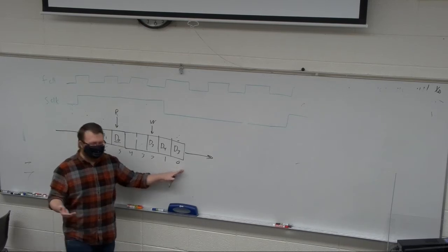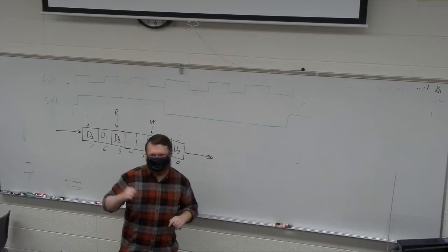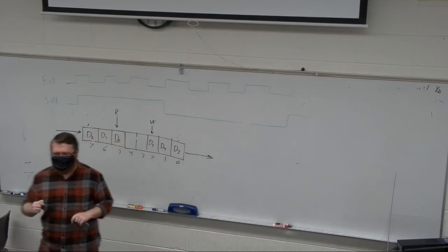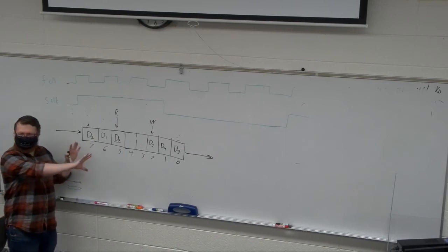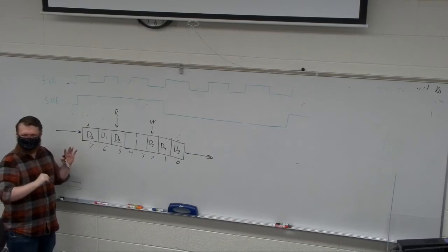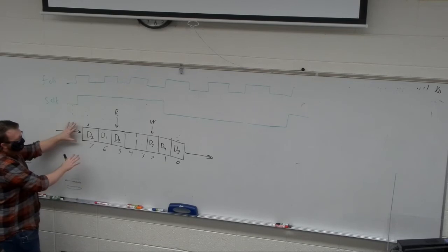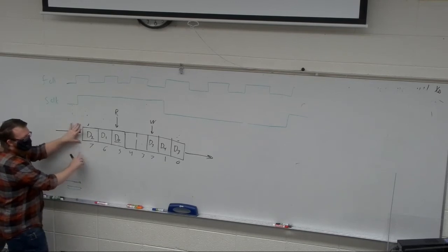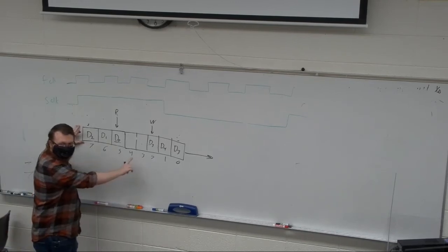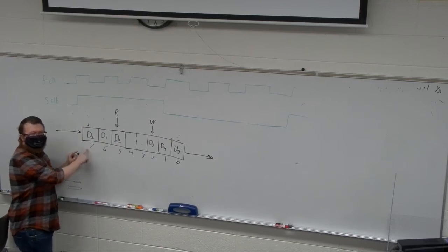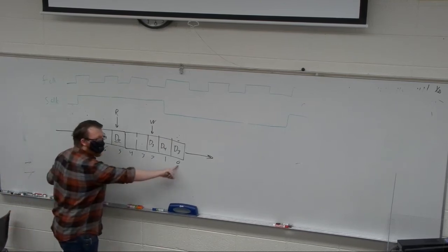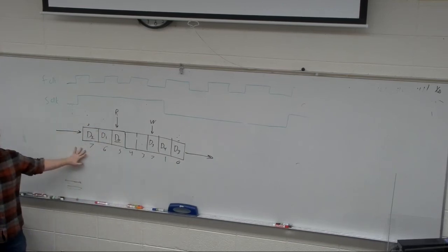So you can have these race conditions. Say that we're doing the slow to fast FIFO. Well, if we have a slow to fast FIFO, we can still use that same type of implementation where we do the metastability dual clock or dual flip-flop, right? But what we don't want to have happen is as we roll over, it pulls in one of these random datas in the FIFO, which could happen if I'm trying to update all 1s at the same time. Whereas if it's gray code when I roll over, it only changes 1 bit.